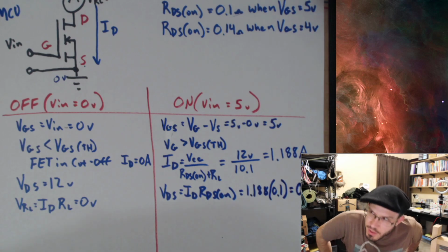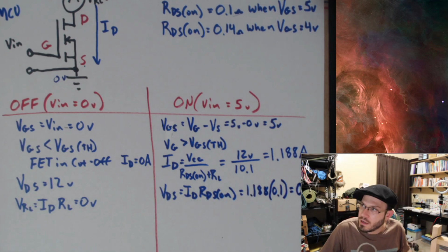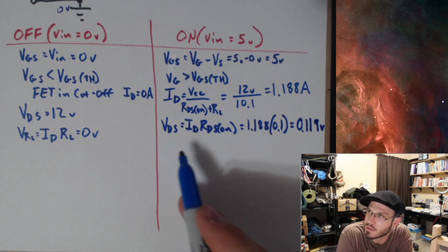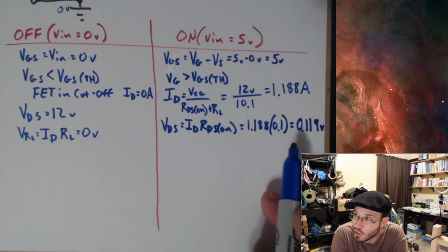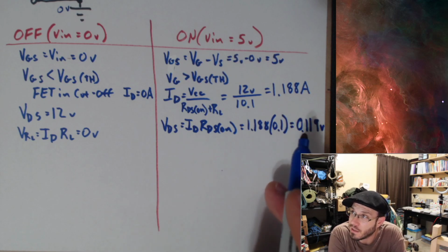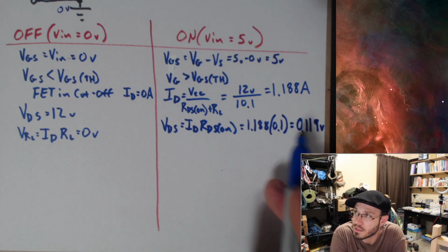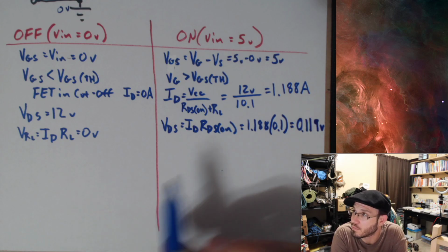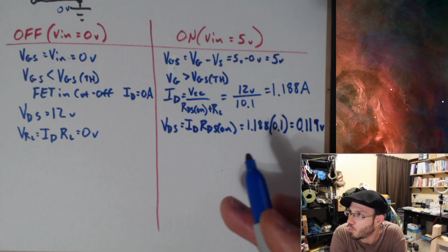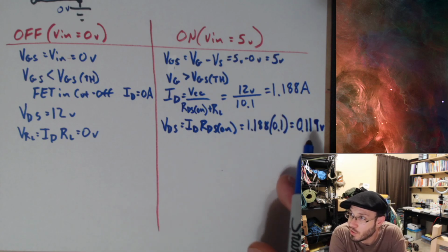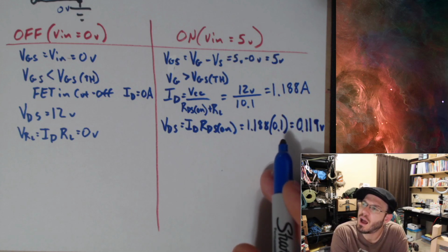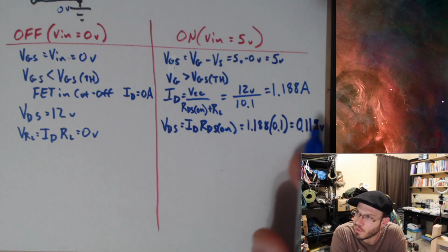Okay, so you can already see we actually have a pretty small voltage drop across the MOSFET. That is good. Ideally, I'd love for there to be 0 volts across it, but I'm never going to get that. But what I can do is hope for a very small value. And 0.1 volts, actually, is a little high. When I use these, I typically get much lower.